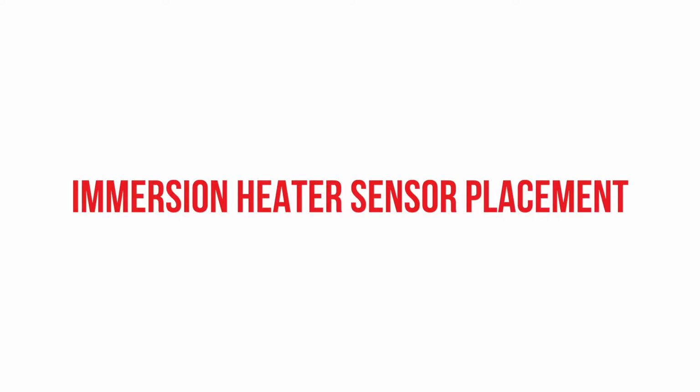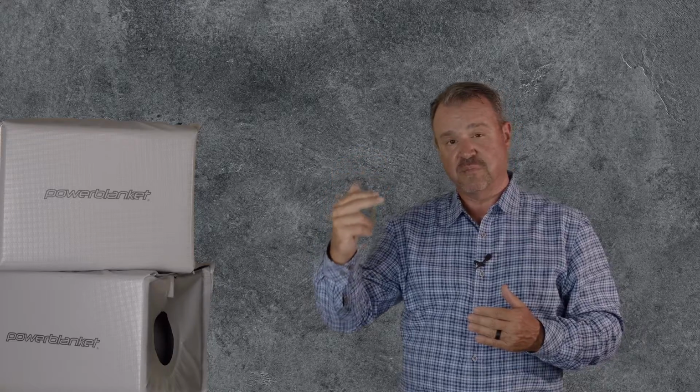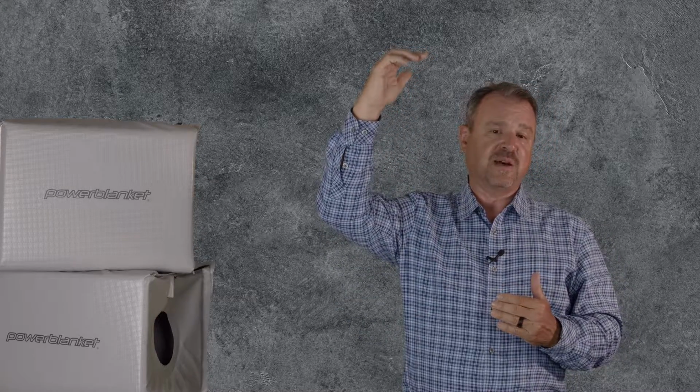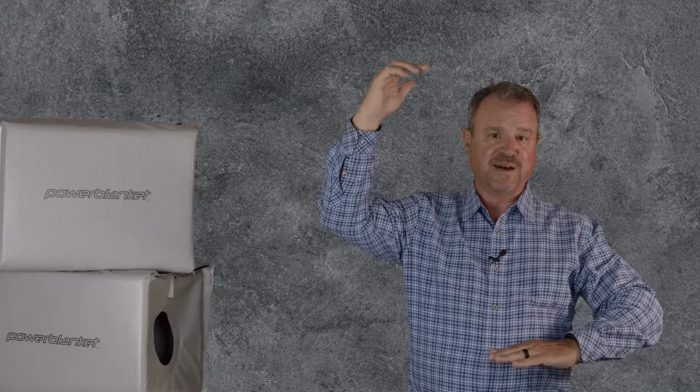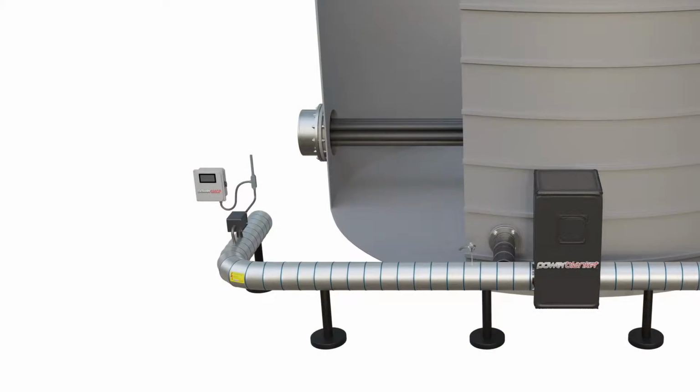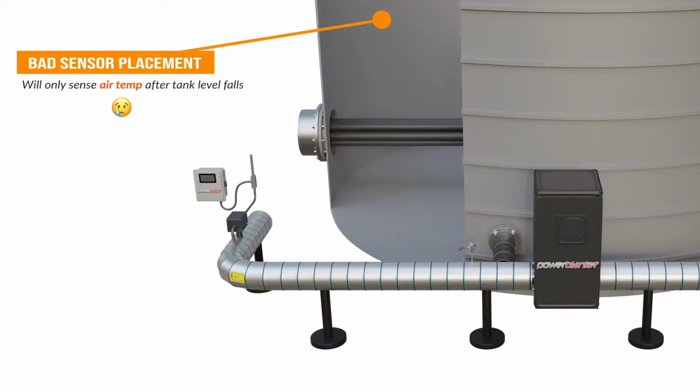So in the thermal loop, the sensor plays a critical role in making sure that it is measuring the temperature of your product where it needs to be measured. In a tank, it often occurs that a person puts a sensor way up at the top of the tank and the heater's way at the bottom of the tank. If the tank level goes down, then the sensor is actually sensing air temperature and not liquid temperature.